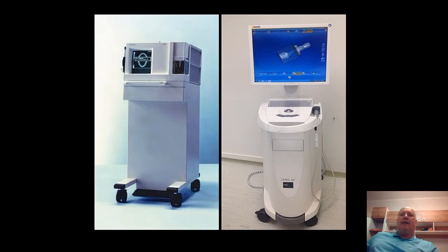In 1987, CEREC 1 was released, which included an optical extraoral 3D camera and a computer module with controls and a milling device, all together. The milling unit had 4 degrees of freedom, and the processing was carried out using a diamond disc. It should be noted that this device didn't grind the chewing surface, so it was formed by the doctor in the oral cavity after fixing the tabs.